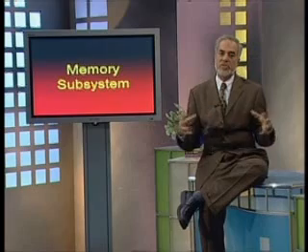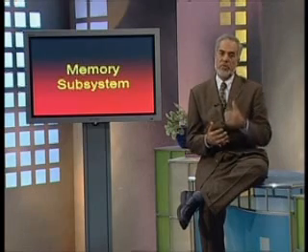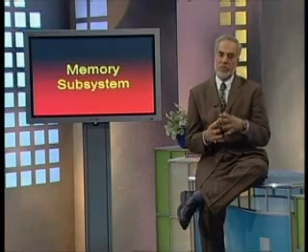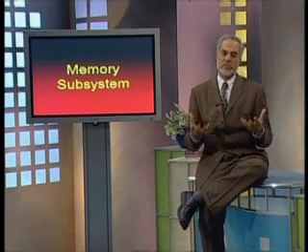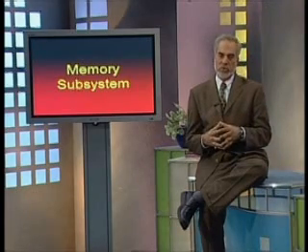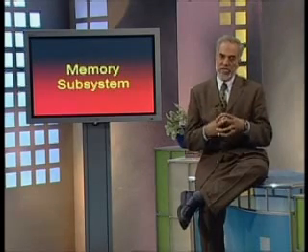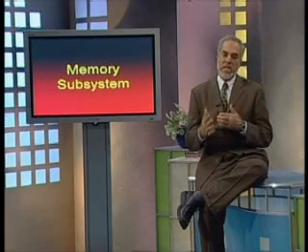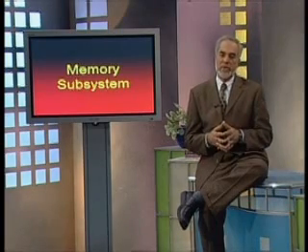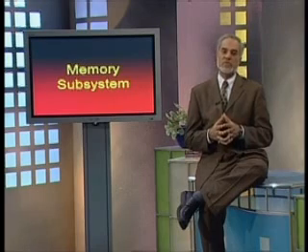So the communication to and fro from CPU to memory and memory to CPU would take place through the load and store instructions if it is memory mapped, and if it is non-memory mapped, in and out instructions could be available, depending upon which particular processor we use.